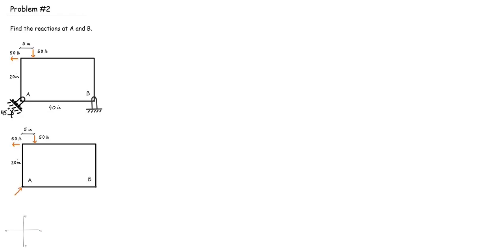So now drawing the forces. The reaction force at support A is perpendicular to the surface because it's a roller. From geometry, we know that the angle between the vertical line and the reaction force would be equal to our given angle, which is 45 degrees. Finally, at support B, we would have the x and y components of the reaction force because it's a frictionless pin. Now, taking the moment about B, we can find the reaction at A.